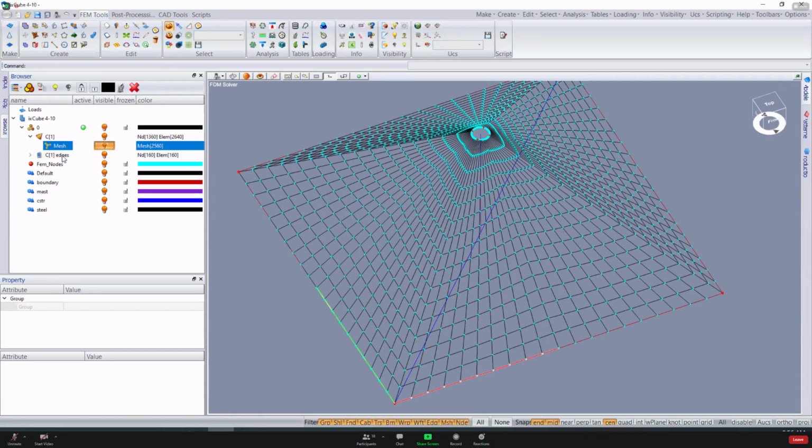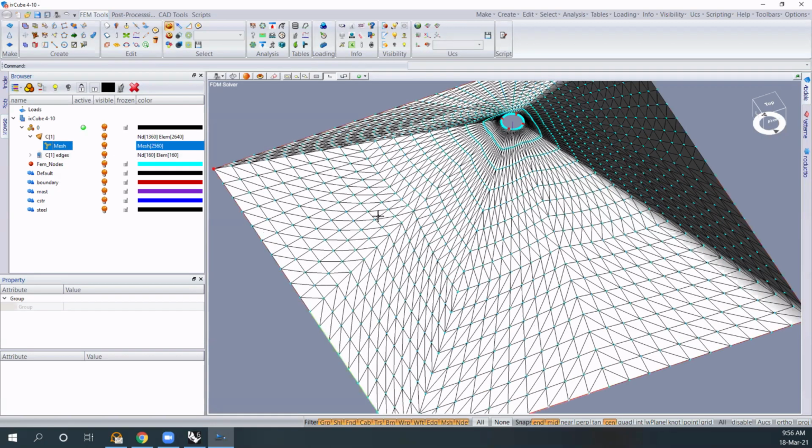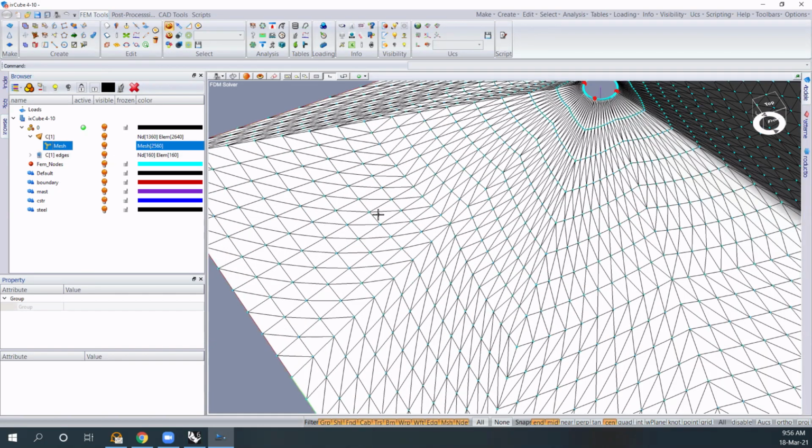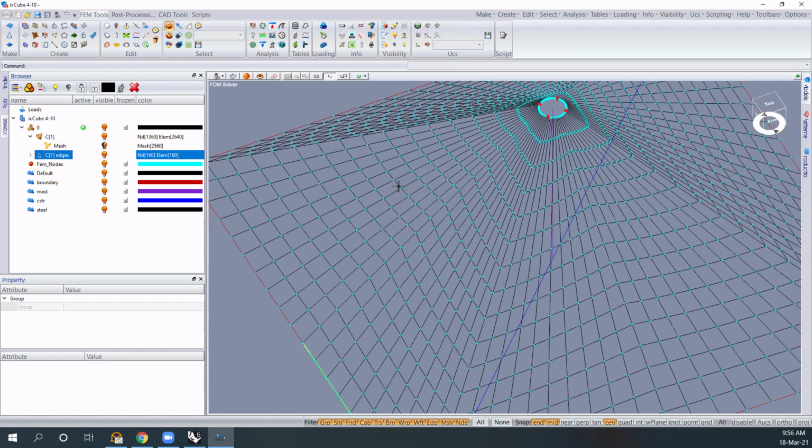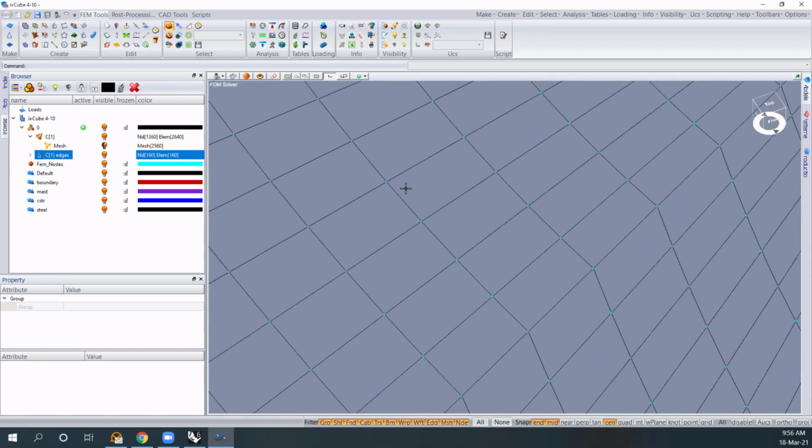Then we have a mesh. This is a mesh made out of triangles, and this mesh is used when we are using the force density method. We use the mesh for applying loads: wind loads, pressure loads, snow loads. And then we use it for making patterning. Clearly, we cut the mesh, making out patterns. But the mesh is not a structural element. The structural part is these links of membrane.